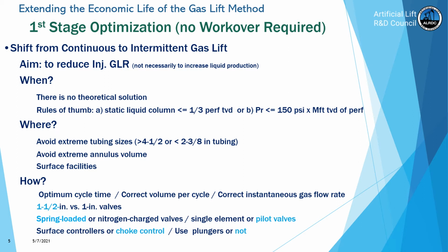The problem is that they tend to give an actual spread that is lower than the theoretical value, the one that we calculate, and that has to do with the dynamic behavior of the gas lift valve. It's not unusual to get a 30 to 50% reduction of the spread of the valve, because the closing pressure of the valve tends to be higher than the theoretical closing pressure of the valve.